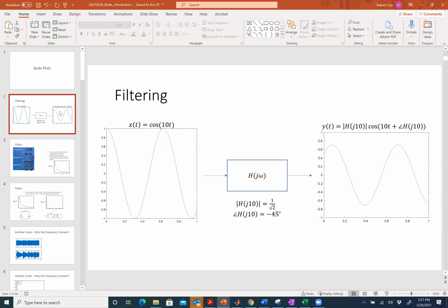But if we're only interested in what we call AC steady state, which means if we have sine waves only, and we're only worried about the steady state, then in that case, what do we do with S? What do we set S equal to if we only care about sine waves? Hopefully you know this. This is what you've been doing on problems 3 and 4 on the homework, you set S equal to J omega, right? And then everything is the same.